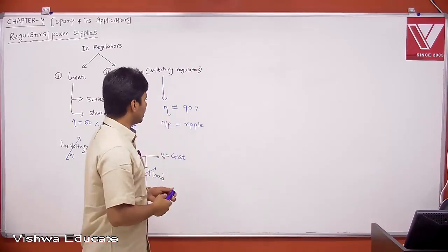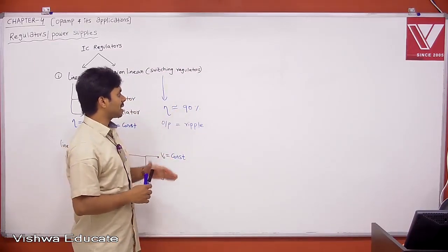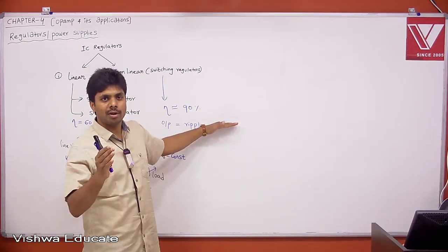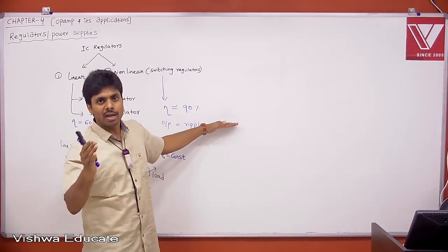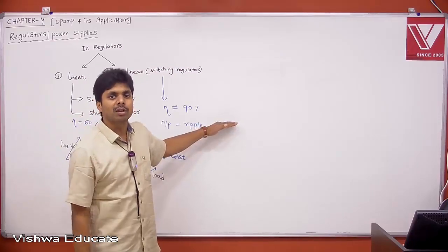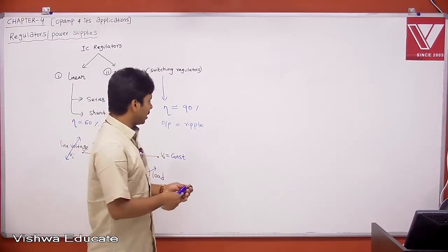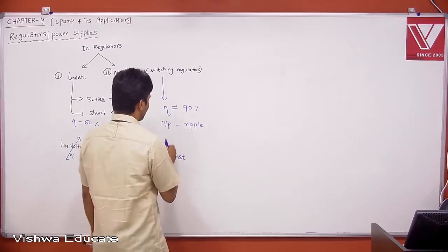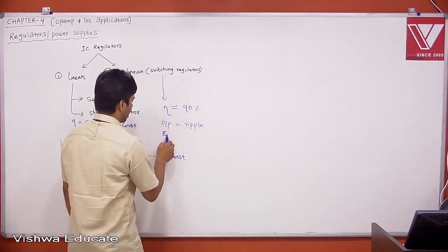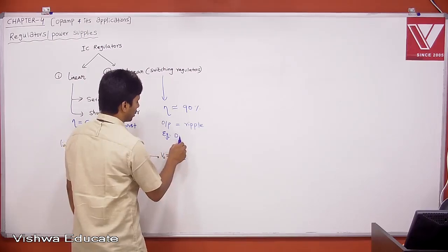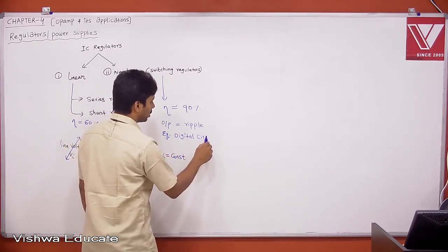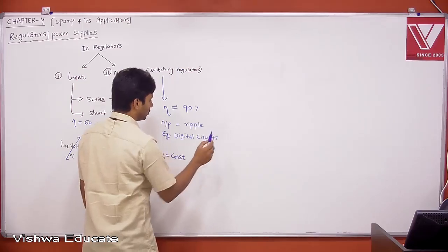Therefore, even though you expect a clean power supply, let us say I am expecting 5 volt, and it is not 5 volt but 5.5, 4.5, 5.5, 4.5. If it is switching between 5.5 and 4.5, you still treat it as logic 1 only. Therefore, I can give you an application: people use it for digital circuits. But not all digital circuits.